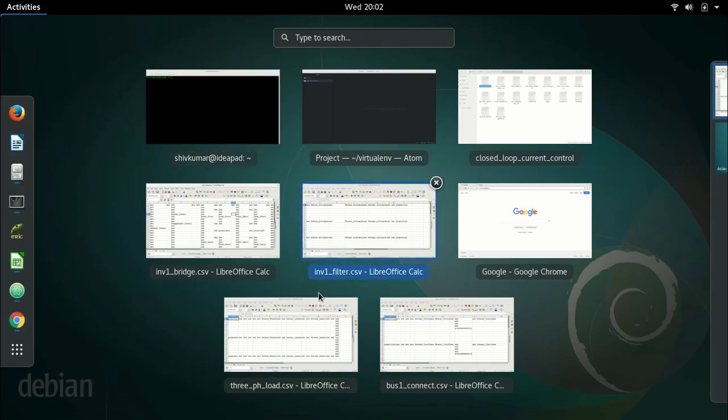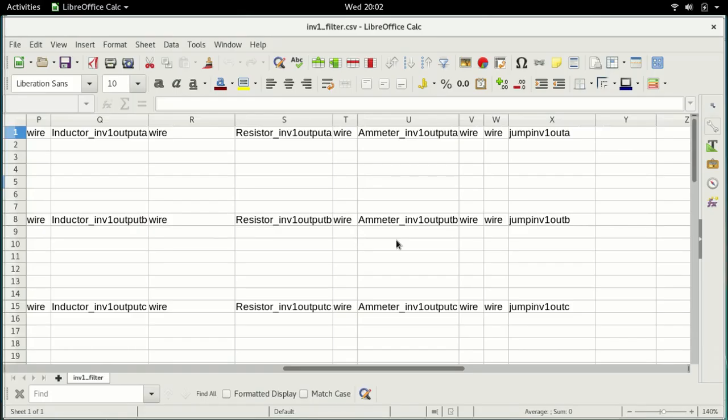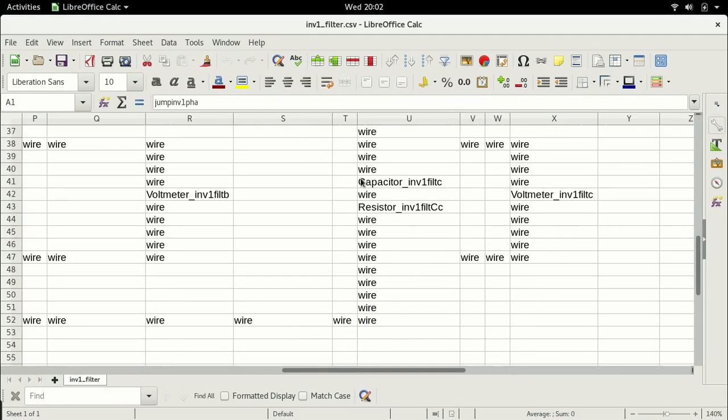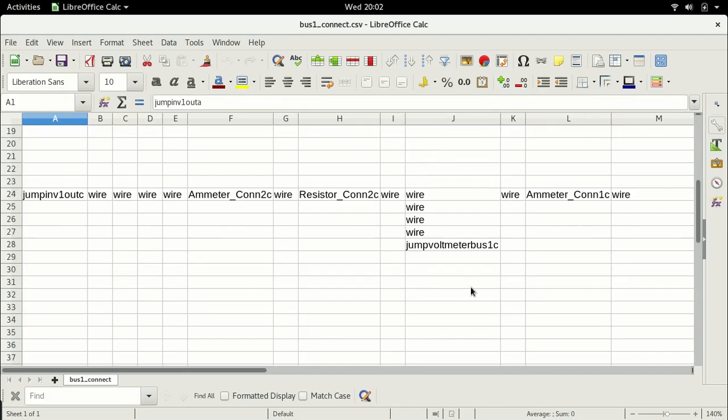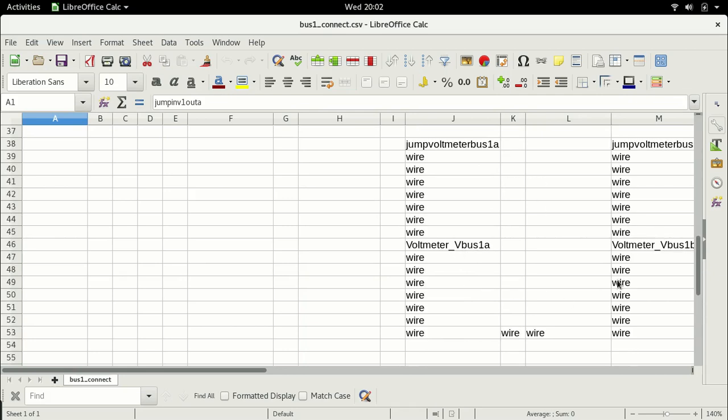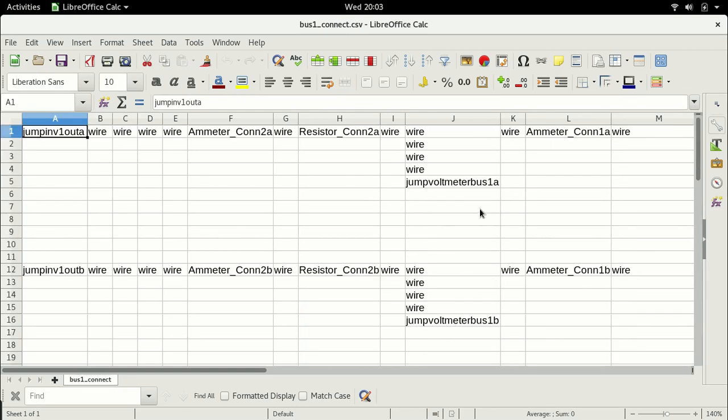So rather, you would regulate either the voltages across these filter capacitors, or the voltage that this feeder sees. This feeder again is voltmeters connected in a star. So if you can regulate the voltages that these feeders see, you are regulating the voltage of the system, and that's what we eventually need to do. The problem is we can't go there directly, and I'll tell you why.